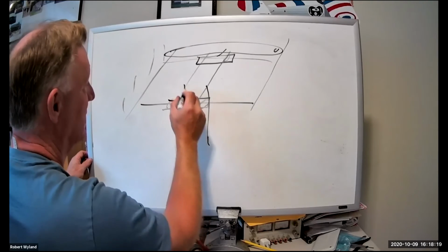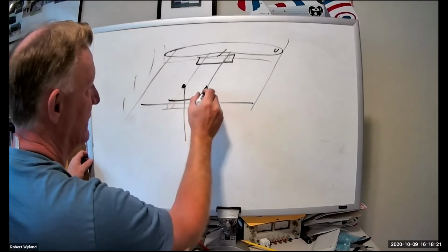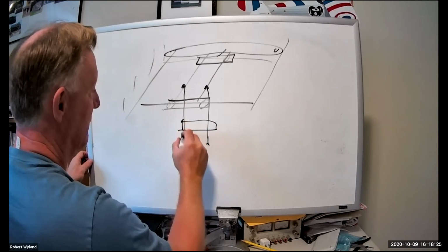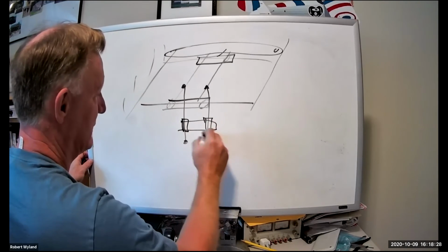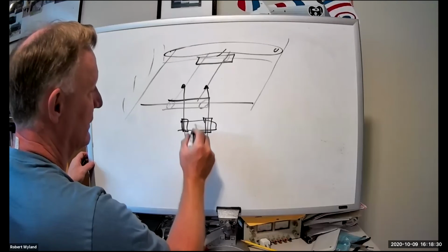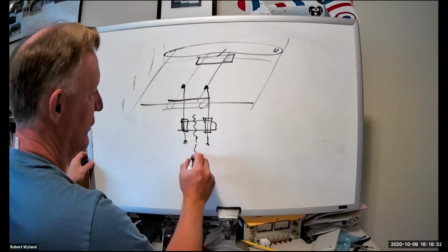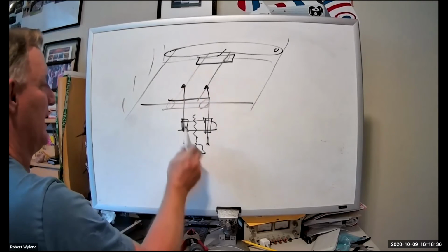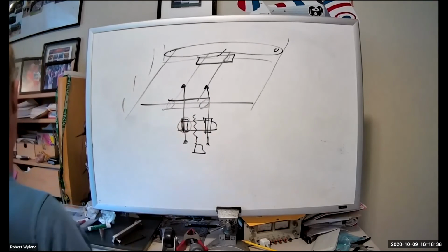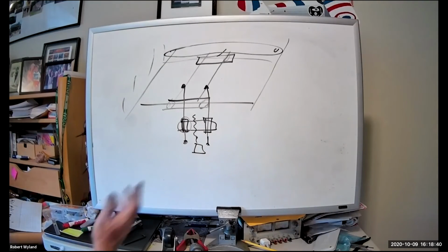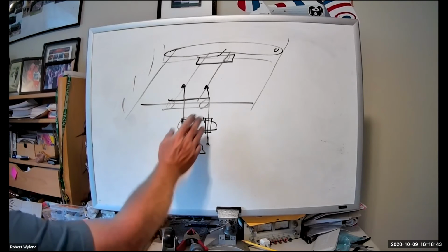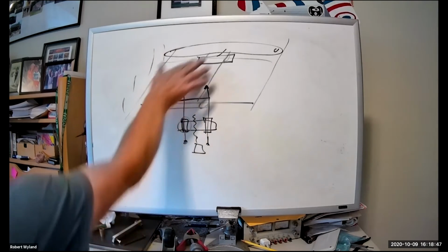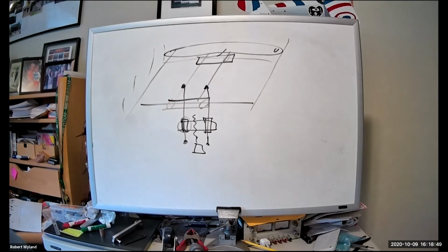They'll have an attachment, and then they'll have another carriage with plain bearings. And again, some sort of either lead screw for the motor, usually a stepper motor, so they can drive this up and down. So this connection right here is oriented in Y or X or Z, depending on how you do it. But basically you end up being able to, at each moment, slide in only one direction, depending on how you've arranged things.